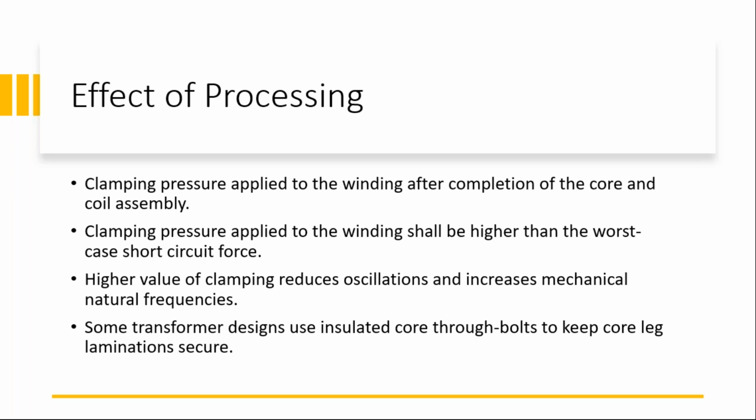In the old conventional way, these bolts were metal, but with the technology the industry has acquired in recent years, these bolts are insulated fiberglass most of the time, and sometimes they are avoided. Adding these through bolts makes the job better for short circuits. So if there is a choice, engineering would use core bolts to give better short circuit strength.